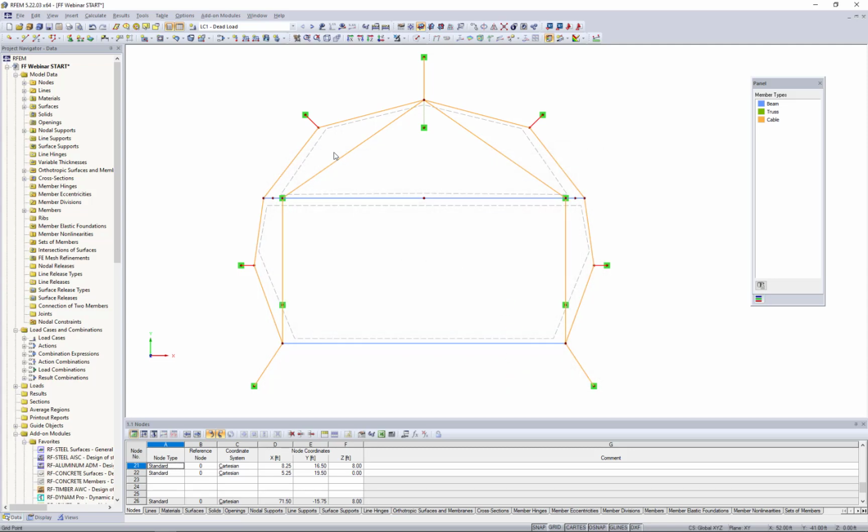So if we're curious to see visually those pre-stress loads defined, what I can do is select RF form finding from my drop-down box here and turn on the display of my loads. So we can see how those pre-stress defined loads apply to each cable element. This is just a good way to check to make sure we didn't miss any of those cables.